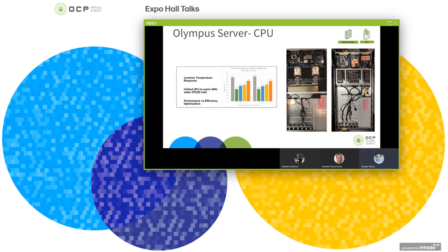One thing to point out, though, in this slide, as you can see, there are cold plate or liquid-cooled modules on almost most of the components: CPUs, DIMMs, M.2s, and FPGAs. And this affects the heat pickup ratio between the air and the liquid. But in reality, that decision has also to be TCO driven, taking into account the power reduction because the fans ramp down further. However, we need to take into account the effect of the added cost for the extra modules.